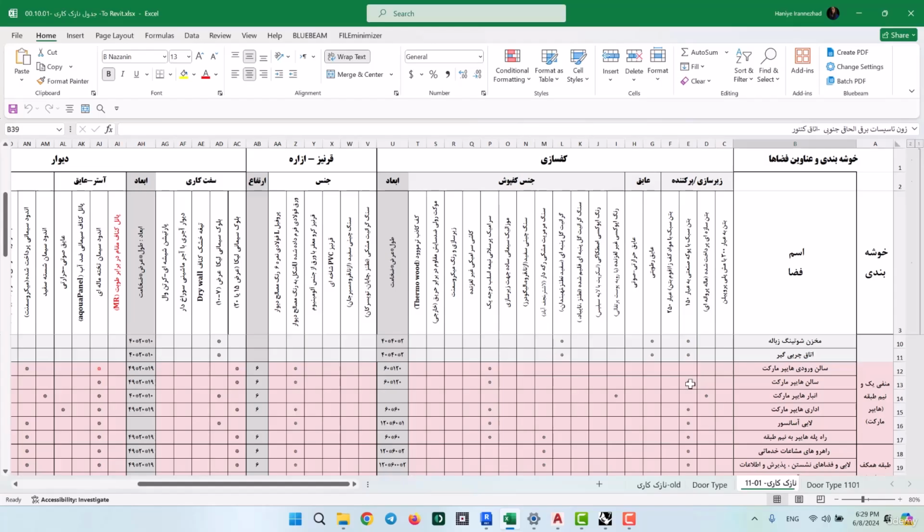But also here's another thing, which is that should we start with flooring and then have the wall finishes go on them, or is it that we place the finished walls first and then the floors? You see, that really depends on your project's installation details. For example, there are some projects where first you need to place the finished walls, starting from the TOS level, and then you get to the flooring process. So the walls are going to be surrounding the floors.